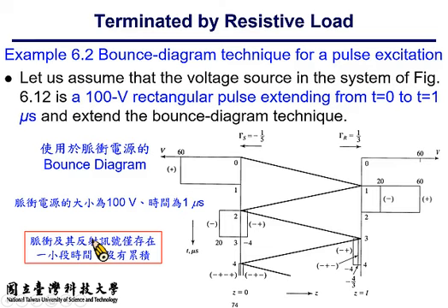However, the V plus signal that appears between 0 and 1 microsecond reaches the load from 1 to 2 microseconds. It shall produce a reflected signal of 20 volt, the V minus signal going from right to left, and it will produce the following V minus plus signal of minus 4 volt. And it will produce another signal of minus 4 over 3, and so on and so forth.